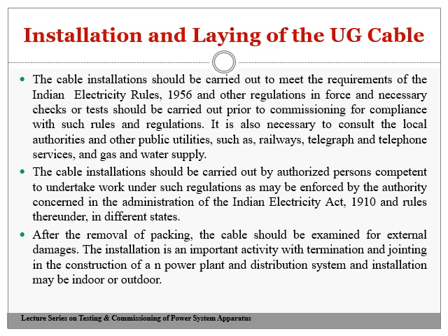Let us go one by one. First, cable installation should be carried out to meet the requirements of the Indian Electricity Rules. As you know, the Indian Electricity Rules of 1956 give many guidelines for electrical installation. Therefore, the cable installation should meet the requirements of the IE Rules of 1956 and other regulations in force, and necessary checks or tests should be carried out before commissioning of the cable.